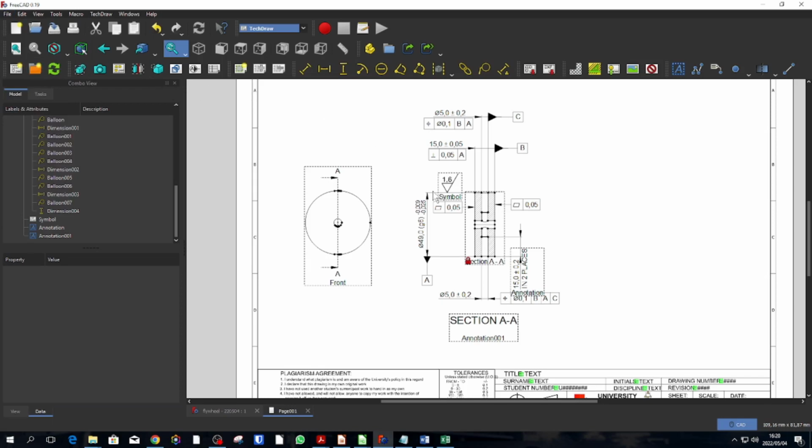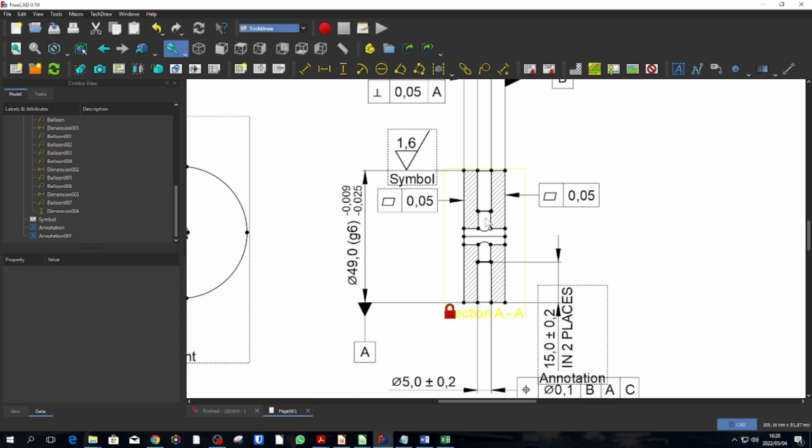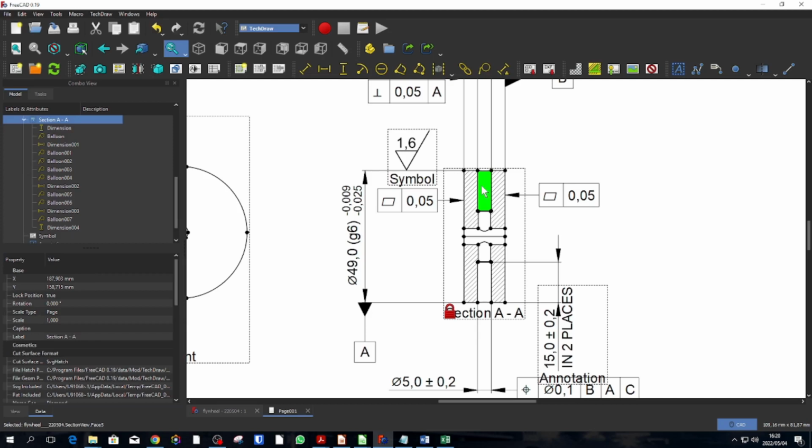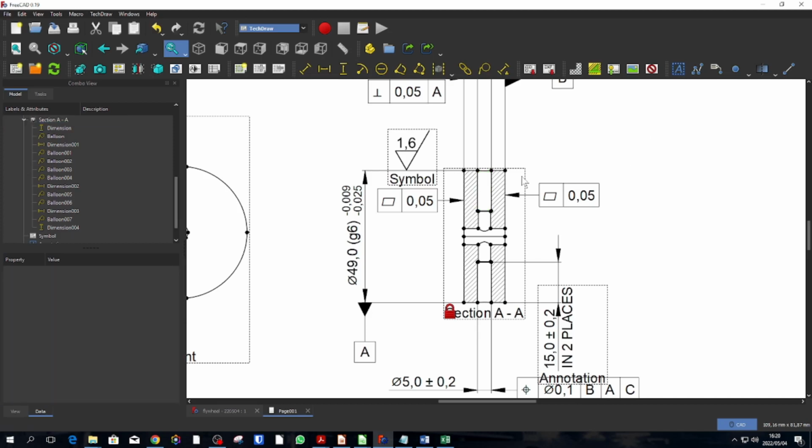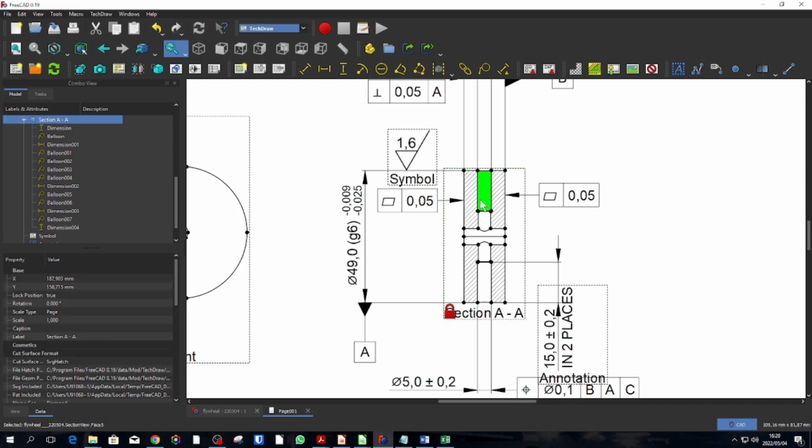Perfect. Alright. Now, the only portion that we haven't dimensioned is the tapped hole. We didn't dimension the tapped hole. And there's also one other thing that we didn't do here, and that is to add center lines. In order to add the center line, you can select that surface over here, press and hold Control, select this surface, come to this button over here, insert the center line to faces,